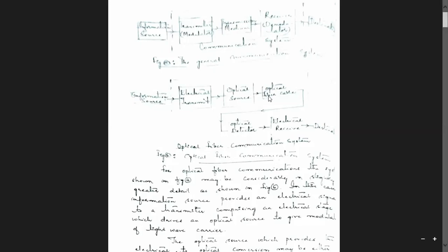So here we just have got single mode optical fiber cables and multi-mode optical fibers as the categories of this optical fiber cable. Therefore, I said that if at all you are using this laser, then in that case we need to use that optical source which has got lesser core diameter. So it means that we can use the single mode optical fiber cables because these single mode optical fiber cables have got lesser core diameter when compared to multi-mode optical fiber cables.